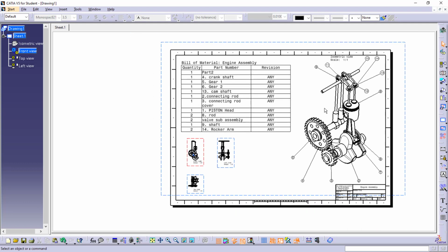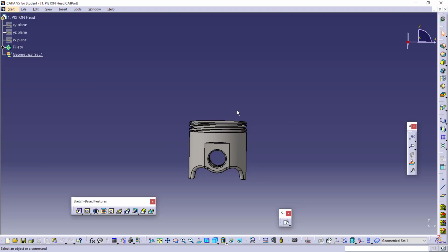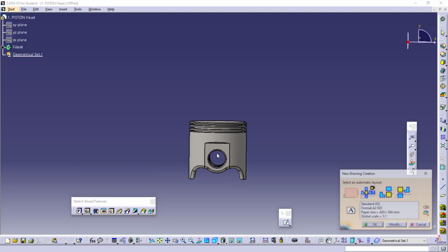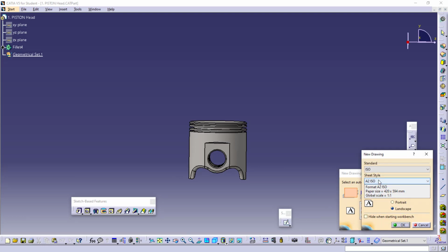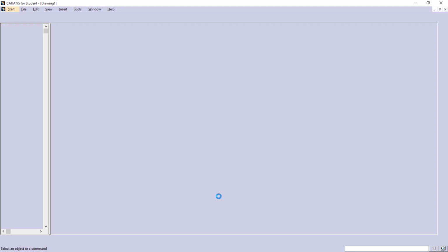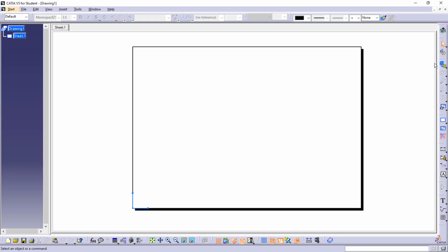Now when it comes to the part, you can open the parts and do the same thing. So let's say this is the component part level drafting. I'll go with the same drafting again, so this component will be taken there by default. The sheet size, I'll go with A3 as it is a part, so small is fine. And now the views, I'd like to have the isometric view first, or else the front view is fine.